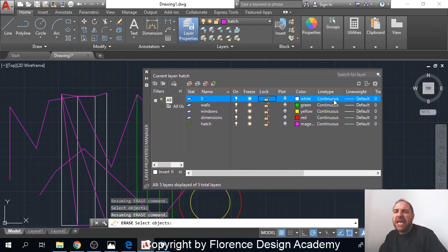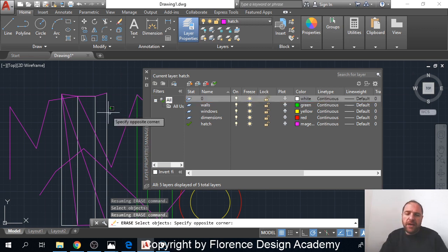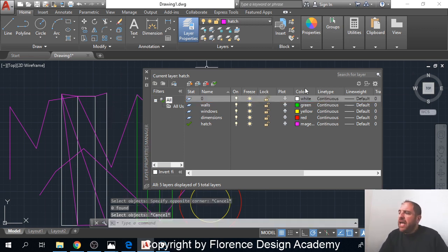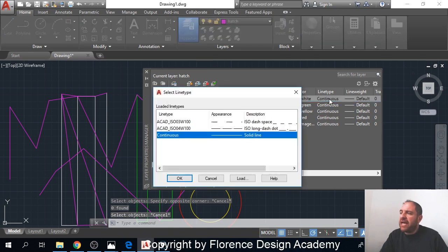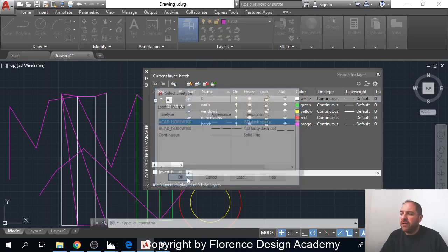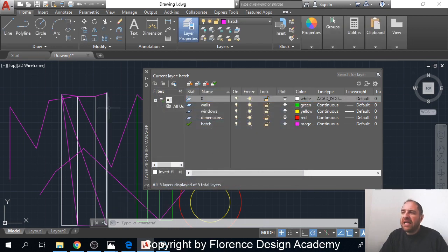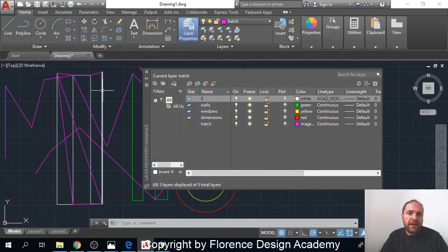I should show you how changing the line type works. Right now it's not super useful for the homework, but we can see that if we have made something, and then we change the line type in our layer, let's say we make it dashed, and we click OK, at the very beginning it looks like nothing is happening.